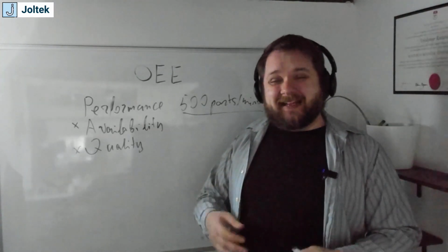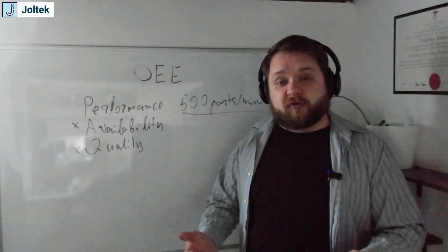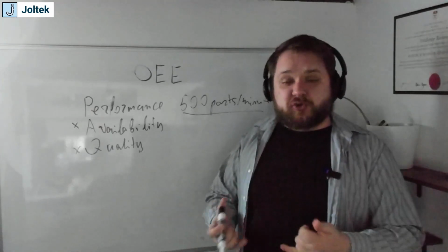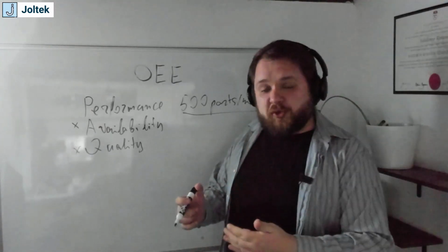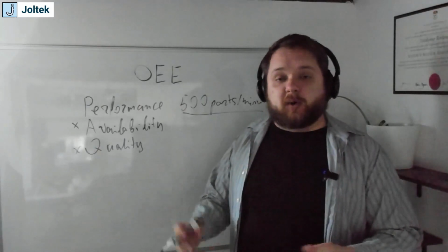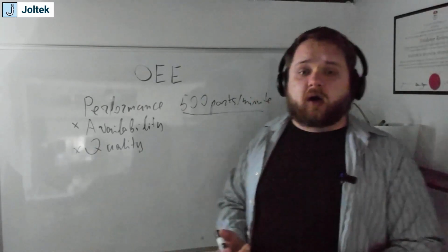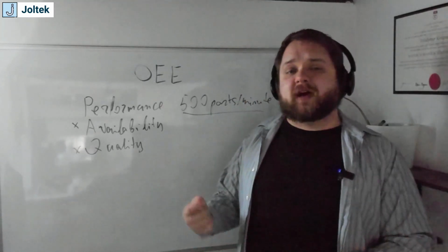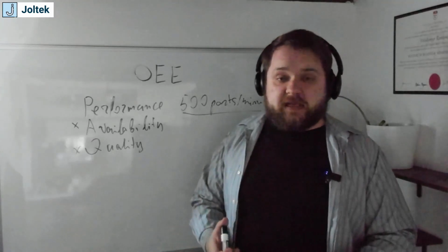Because like I said, the machine does not physically know whether product is going through it. It is just executing cycles. So sometimes you need to capture and synthesize both of those pieces in order to know the product is going through, cycles are going through, and the machine is putting out quality parts. And the last one, once again, so quality systems, there's going to be a lot on vision systems based, there's going to be sensors. So you should be able to tie in some of those counters from the PLC into your software on the MES layers.